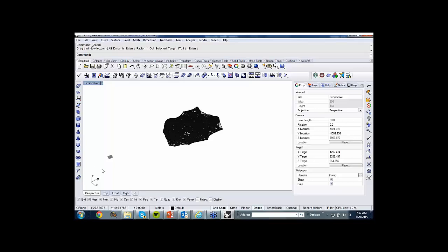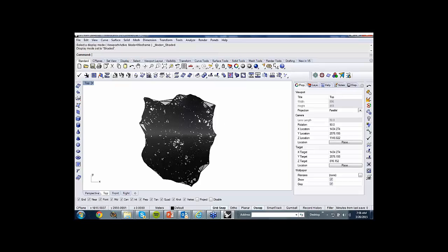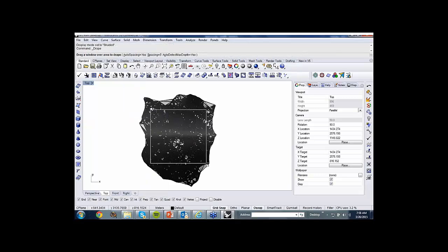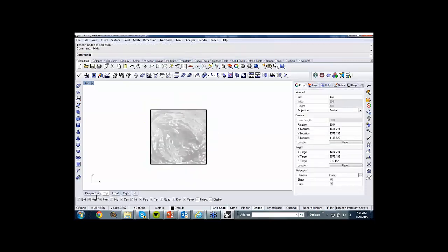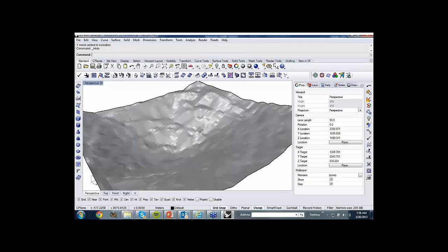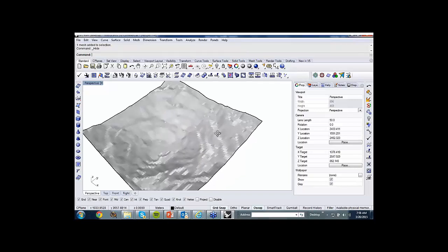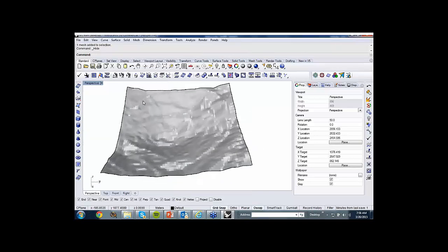But here, in the top view, I'm going to say, turn this object, drape this object. Very simple. Anything you put in there, even a solid, it's like putting a silk tablecloth on this table. So drape, go from here to here, and I draw a curve, and sure enough, now if I hide the mesh, I see I have created this object, which is essentially a representation of that. If you look at this, there are some parameters that define an IJ structure. It grids the surface in the east-west and north-south direction.